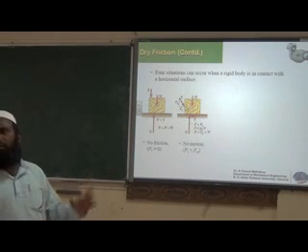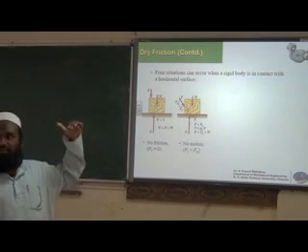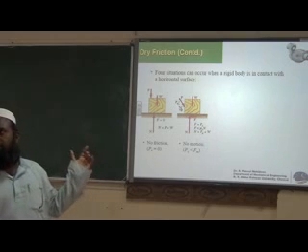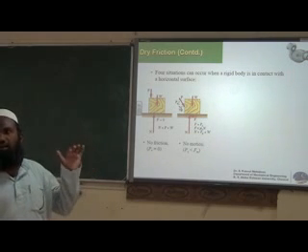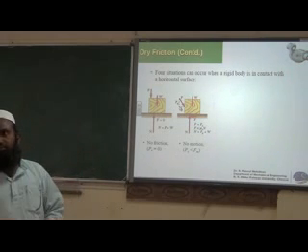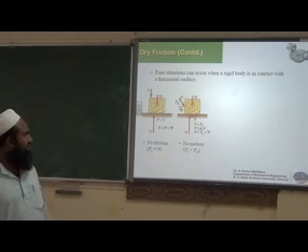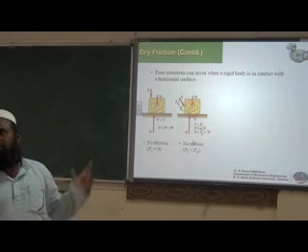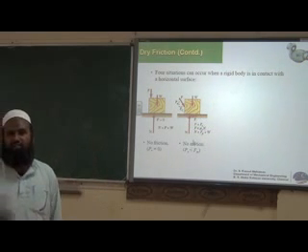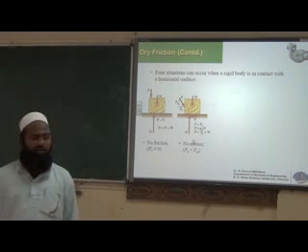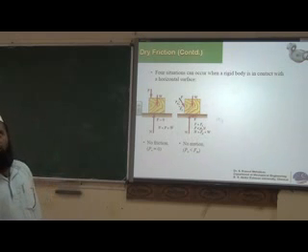This is also a condition where there is no motion, but here there is a horizontal force. Consider force P; it will have two components, vertical and horizontal. The horizontal component will try to move the block, but it will be resisted by friction. As it tries to move the block, there is a resistance provided by friction, F equals mu s times N, but still no motion. This horizontal component is less than the maximum frictional force, so no motion.